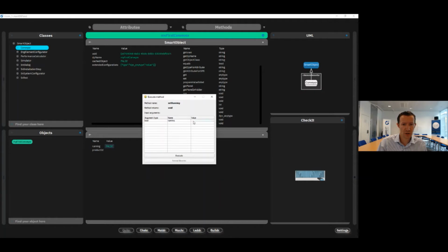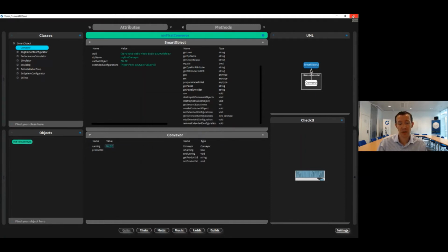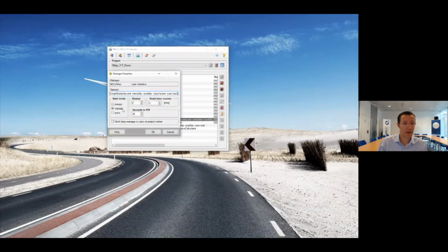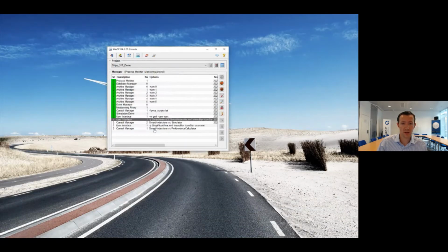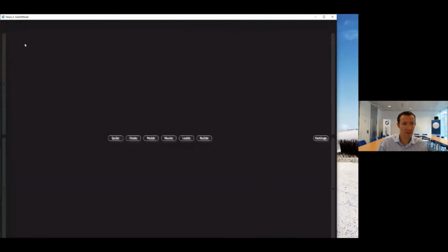And if we try and update an attribute, we should see that it should update, but I'm seeing that it's not. This is due to the fact that these are actually creating WinCC OA libraries behind the scenes. So if I restart that, then it will quickly come back and we can try and simulate that device again.